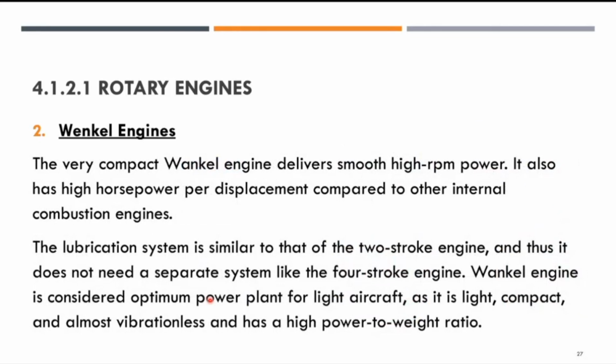All right. So the very compact Wankel engine delivers smooth, high revolutions-per-minute power. It also has high horsepower per displacement compared to other internal combustion engines. The lubrication system is similar to that of the 2-stroke engine, and thus it does not need a separate system like the 4-stroke engine.